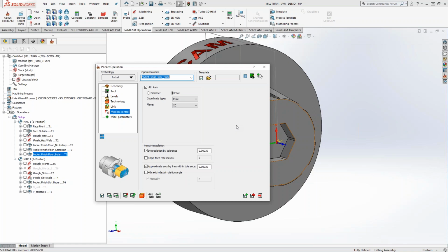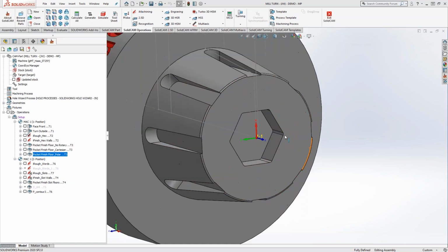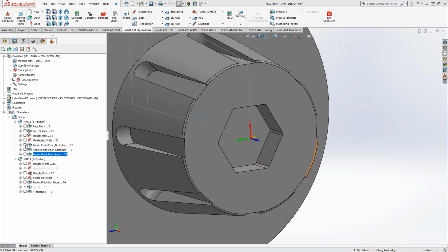Inside the software, it's just a checkbox, and it's of the 2 types. Yeah, and you guys will see the same tool path. Everything's going to be the same. The only thing being affected, like Mark is saying, is just the G code only. Yeah, so if I show the wireframe, it's still doing the exact same pocket. And there's nothing here that would show us pretty much any difference. It's not until you post the code that you see the difference.